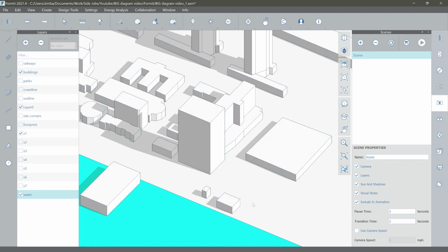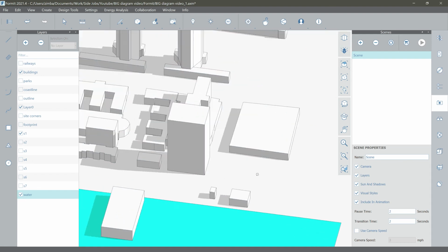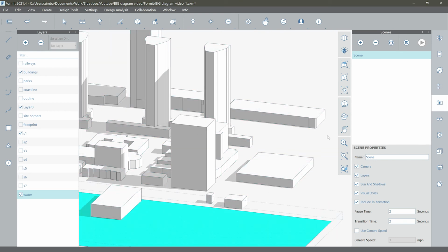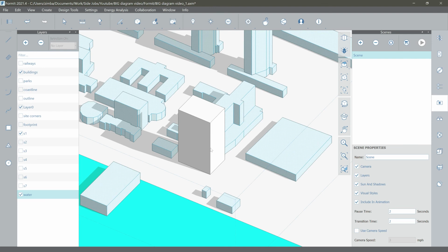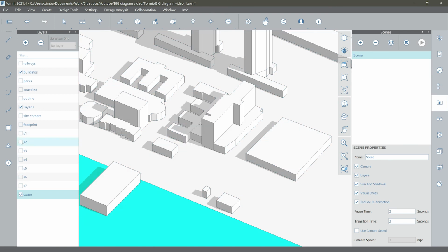What that does is if I switch it around, I can come back up here to the scene, double click on it, and it'll bring me back to exactly where it was before. So you can do this once here and then just apply the different layers that need to be on. That's just a surefire way to not mess up the perspective.